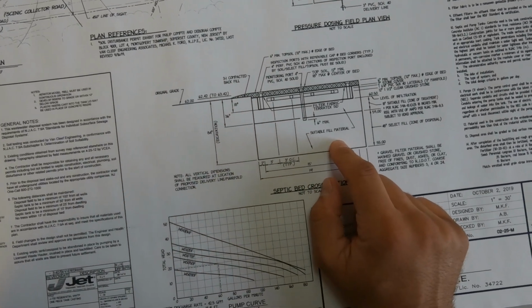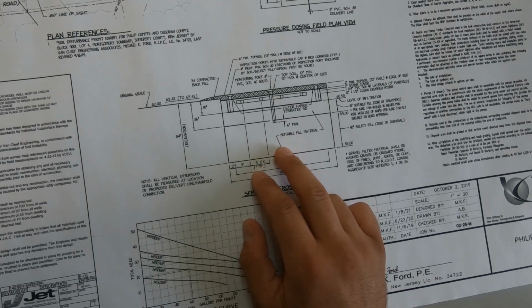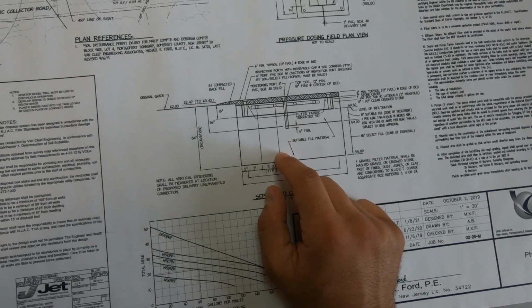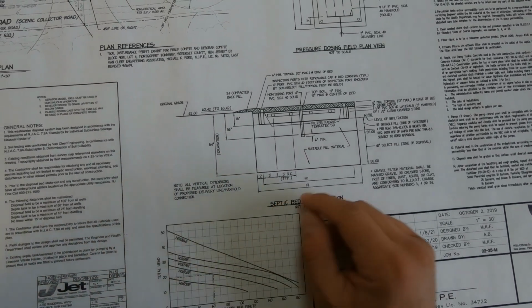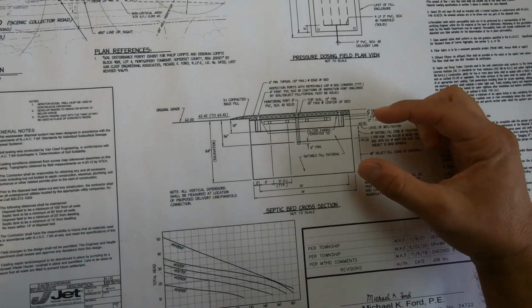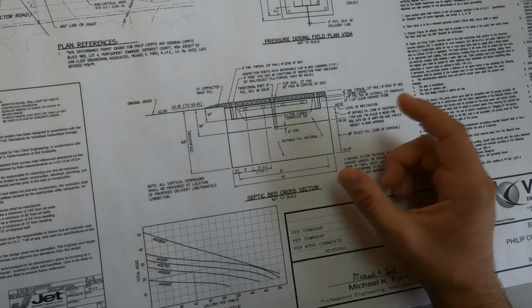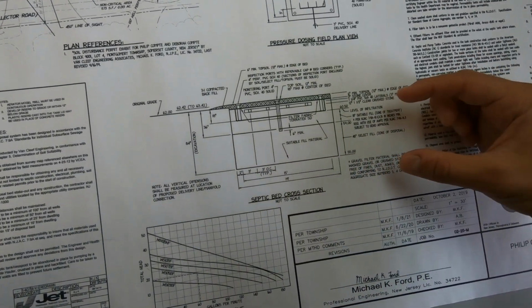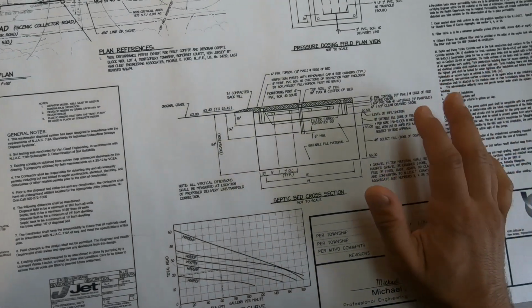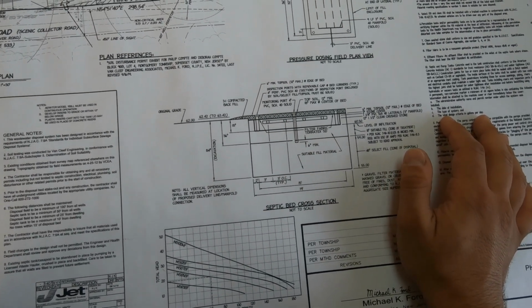It also shows the suitable fill material. So there's 2 layers. We've got the zone of disposal and the zone of treatment. Now, the thickness of these layers depends on what type of system you're doing. If you've got an advanced treatment system, you can actually reduce the zone of treatment, right? You can make that layer thinner because there's some pre-treatment going on. There are also cases where you can make these different fields or these different zones smaller, or you may have to make them larger in some cases. Again, talk to the design engineer. That's their responsibility to make sure that it's being designed accordingly.